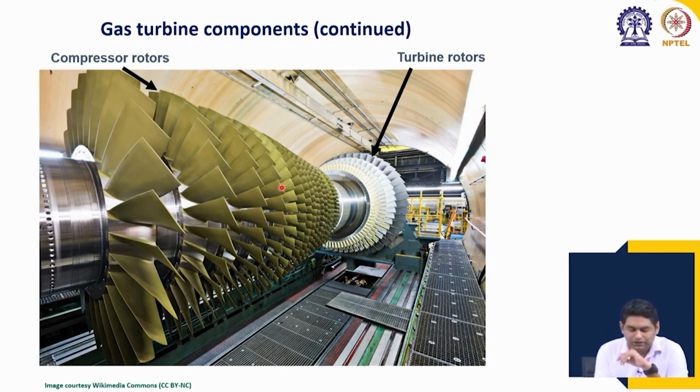These are all compressor stages, the yellow colored ones, and each of these is known as a blade. In a single stage, several blades are mounted around the circumference of the hub or the base of the stage. This is known as a rotor disc. At the hub of the rotor, all these blades are mounted and the rotor itself sits on the shaft. The hub itself is connected to the shaft. So, when the shaft rotates, these blades also move, and while moving, because of their curved nature, they push air in the forward direction, which can be used in the following stationary structures which are not shown here.